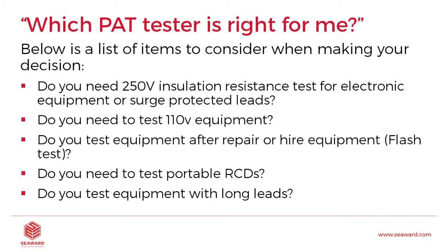Do you need to test 110 volt equipment? With adapters, most PAT testers will test 110 volt equipment, but do you want to power up the 110 volt equipment and give it a run test? Do you test equipment after repair or hire equipment? Because you may require the facility to carry out flash testing. Flash is less common in routine testing, and is not to be carried out routinely at all, because you can put stress on the appliance and eventually wear it down. So it's just after repair and hire equipment and things like that. In the hire industry, they tend to do flash tests if they are changing brushes in drills, for example, and putting the drill back together.